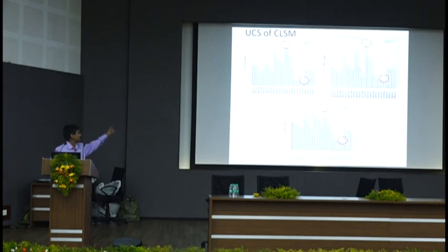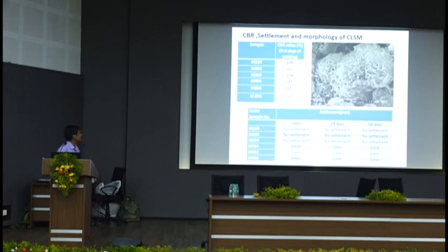These are the compressive strengths at 7 days, 28 days and 56 days. Then these are the values, very high values we got. And then microstructure, obviously as part of research, it's not only this. Now you have the accessibility of SEM and XRD, so you can go for it and see. They show the CSH gel, which is responsible for gain in strength.